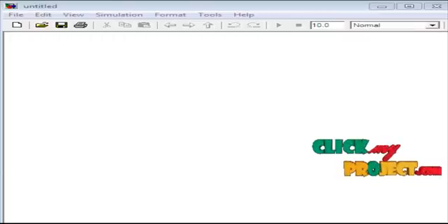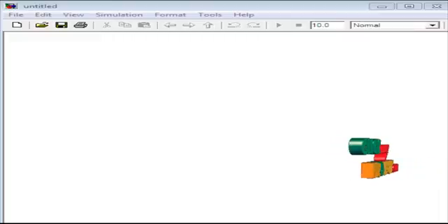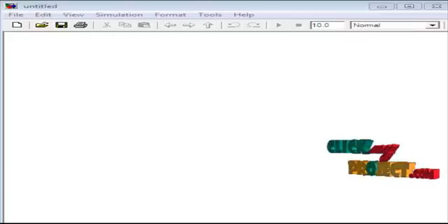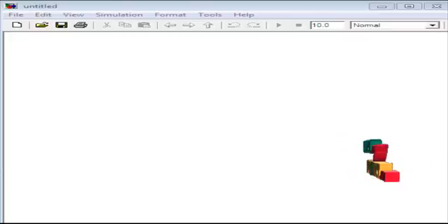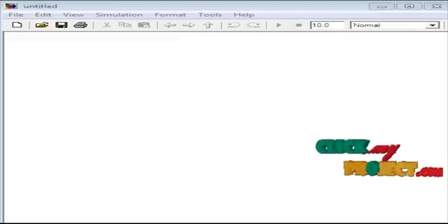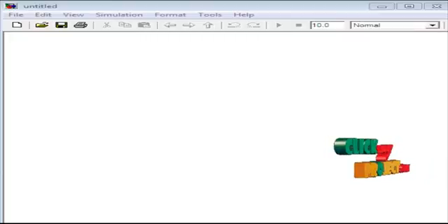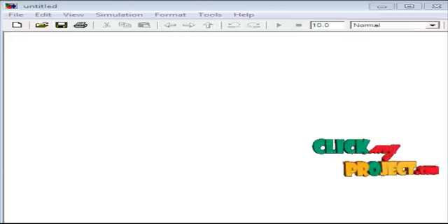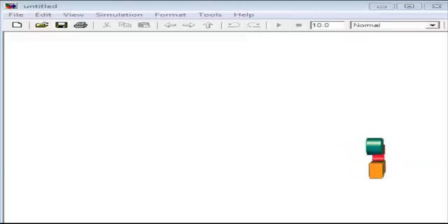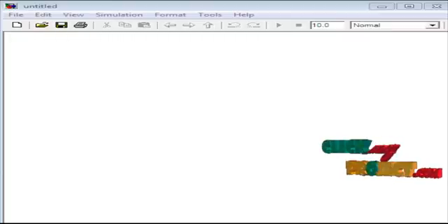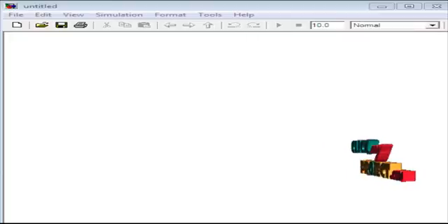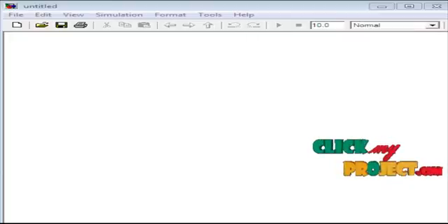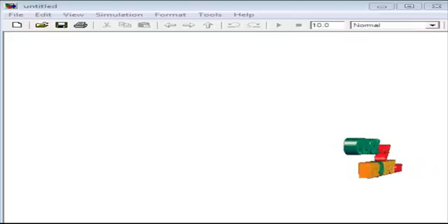The switching transition of the main switch is lossless, whereas the turn off transition of the auxiliary switch is lossy. ZVS buck converter with active clamp. The main active switch S1 is turned on at t equal to 0, following the slope of the voltage turn on and off conditions. The ZVS converters with the active clamp retain the simple features of the hard switched components.